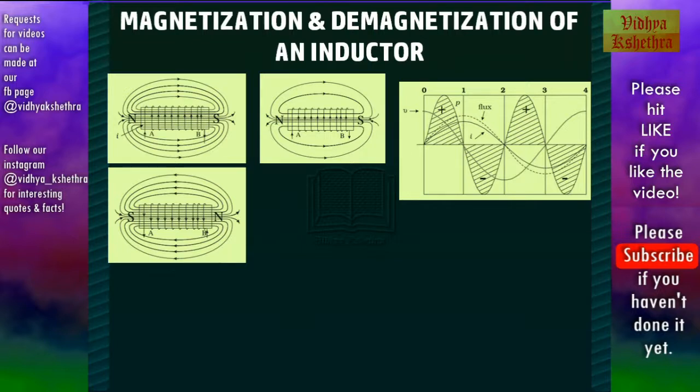In this stage, the direction of current is reversed and hence the magnetization is also reversed. And since the current is increasing in the reverse direction, the magnetization increases and the poles are switched. In this stage, since current and voltage are both negative, energy is absorbed by the inductor.